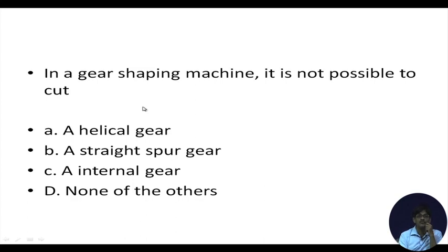And also screw and nut won't be able to give you the reciprocation. You have to have another mechanism, or another type of controls which will give you reciprocation. Screw and nut can only bring about rotation to linear motion, that is not reciprocation.